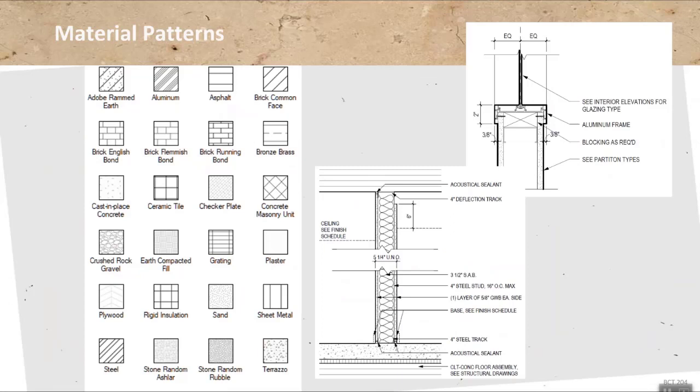You saw a second ago that material patterns are important. Material patterns appear when you cut through materials, either in a vertical or a horizontal cut, and are mostly visible in these details, because once the scale gets too coarse, you can't see anything, and this wouldn't be shown. But these are fairly standard material patterns, or hatchings, as it's often called.